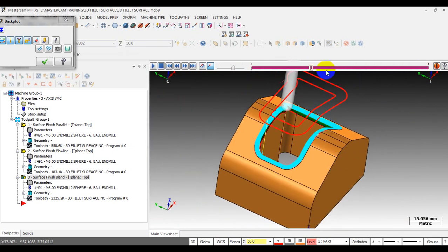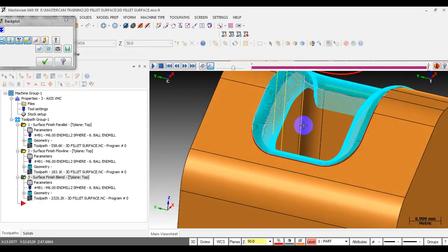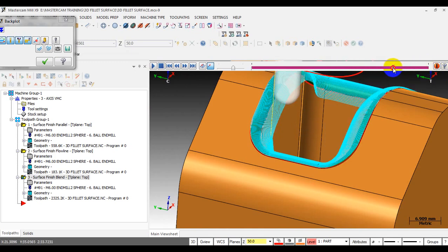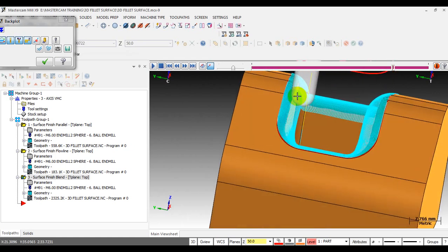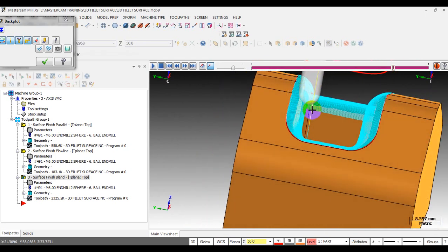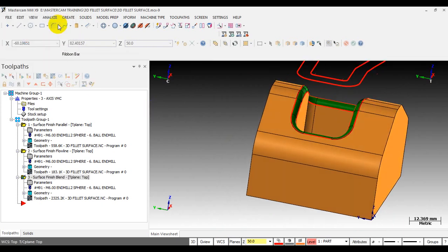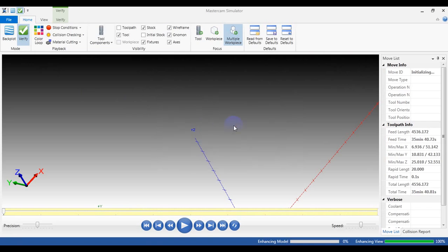By changing the chain, you have changed the whole toolpath. You can see this: the tool center will follow this inner chain and can cut the steep surface here. That's good. We verify this again to see if it works or not. Of course, it works. That's the trick on the plane toolpath.